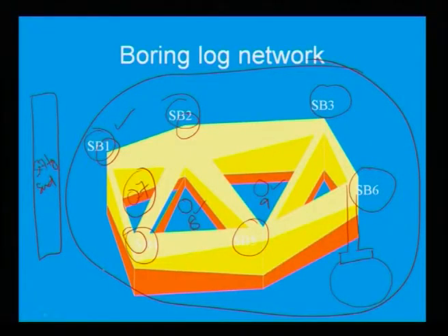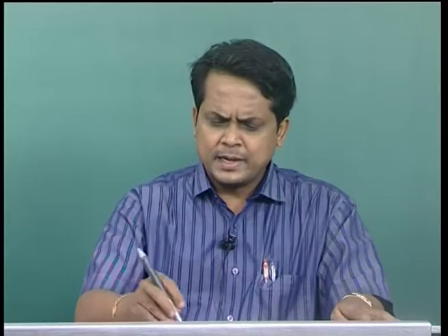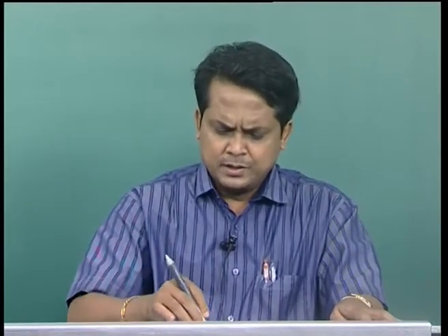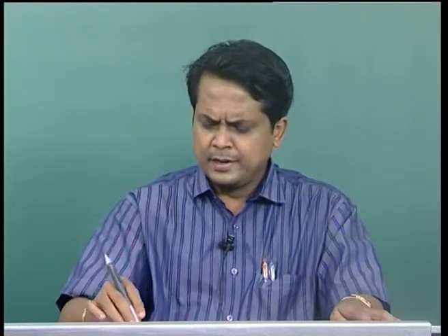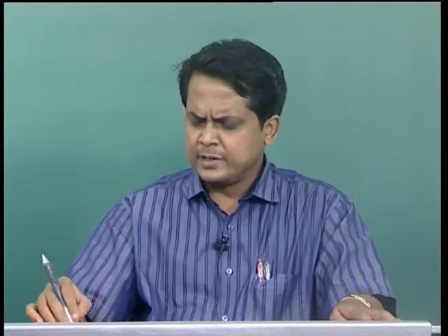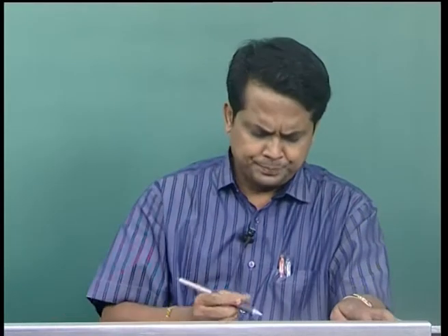Based on that, the strength properties C and phi will change. Whether you consider this or this, generally you will go for the most adverse conditions for this design. This is about how you decide the boring, where you have to do the boring, and if required, how you will decide your additional number of borings to be done.